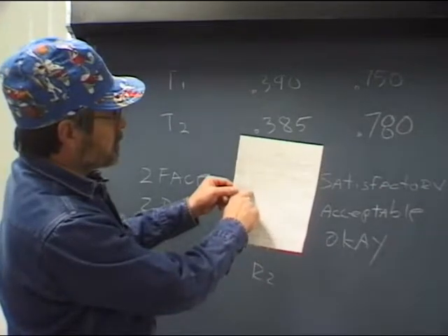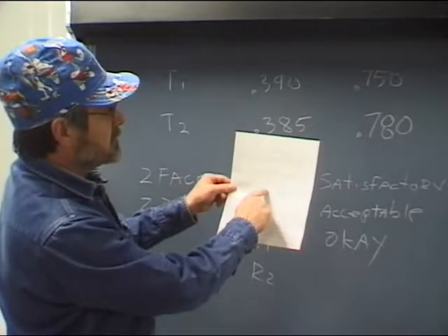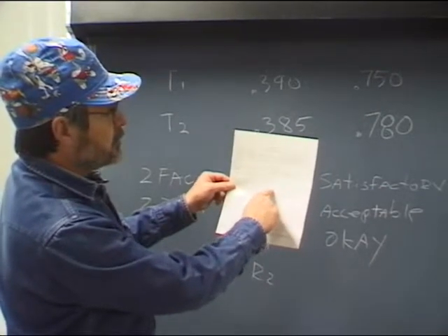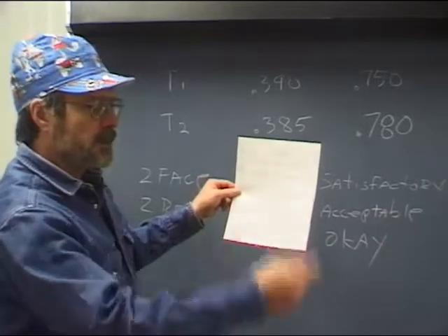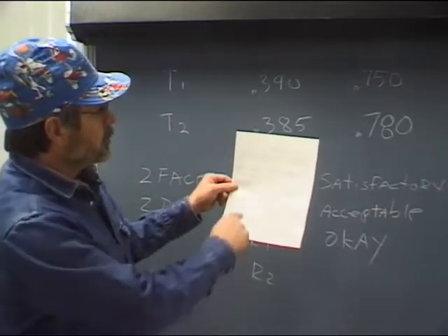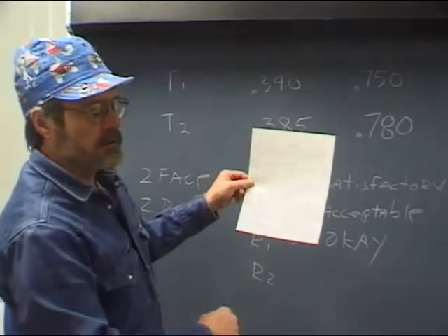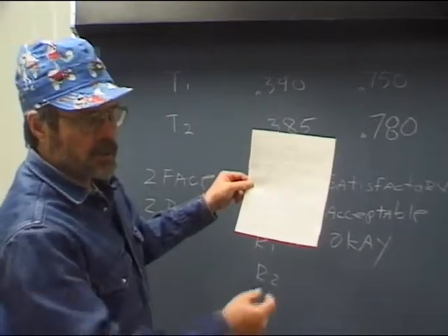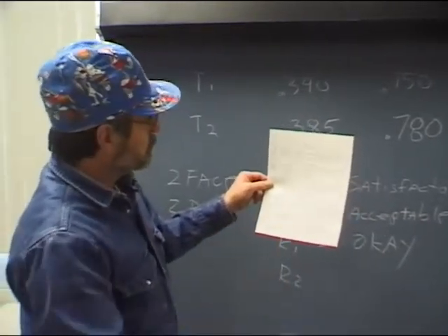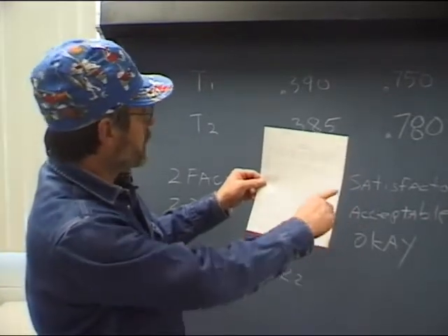And you notice there's notch location, specimen size, the testing temperature, the impact values. If you remember, we talked about some of this testing before. You're going to do these tests in sets of 3s, and you're going to record the actual temperatures when you tried to do the breaks and so forth. That'll all go in there, the drop weight.